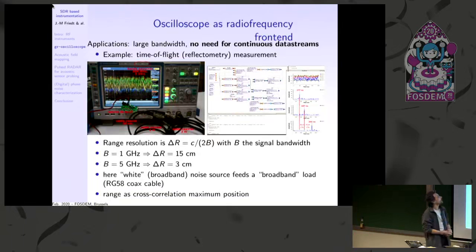measurement. Initially, I was playing with my colleagues, trying to do some software for acquisition, but it took me a bit of time to make a usable GNU Radio interface for the oscilloscope. Now what we're looking at is collecting data from the oscilloscope. You know that the scheduler of GNU Radio is working with kilobyte packets. All of these oscilloscopes have mega-sample memory depth, so what we're doing is collecting a big chunk of data. Of course, for an experiment, you don't claim to be continuously streaming data. You just need chunks of data. But if you have high bandwidth measurements, you still can do quite a lot of things.